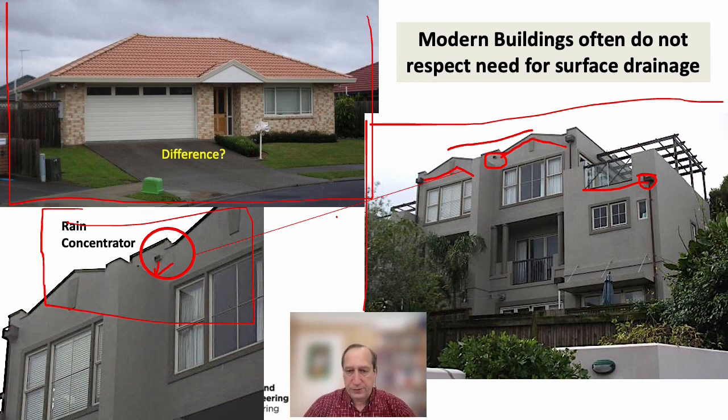First of all, pitched roof. Secondly, low rise, only 1 story high. Third, look at the size of that overhang. All the roof drainage is actually led into gutters or eaves troughs and downspouts that are on the outside of the building. So no chance of concentrated rainwater running through a wall. And of course, I also happen to like the nice steeply sloping yard. Everything is being done correctly on the upper left to reduce the amount of wind-driven rain.